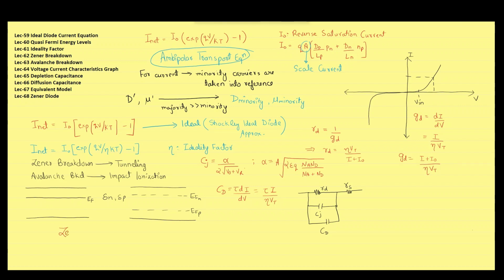Zener diode is a highly doped PN junction such that the breakdown occurs at low voltage. A Zener diode is operated in reverse bias condition. However, if we forward bias a Zener diode, then it will act as a simple diode. Avalanche breakdown is the predominant breakdown mechanism in a simple diode. So, if we want Zener breakdown to be the dominant breakdown mechanism in a diode, then we have to dope the semiconductor with a high concentration of dopant.